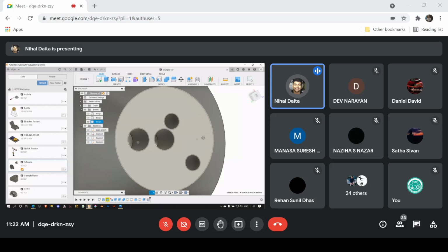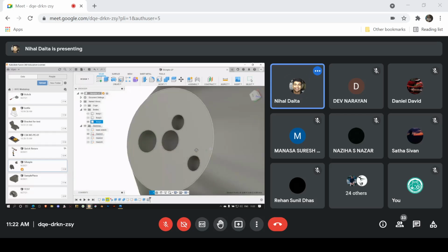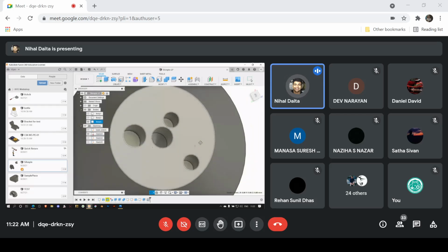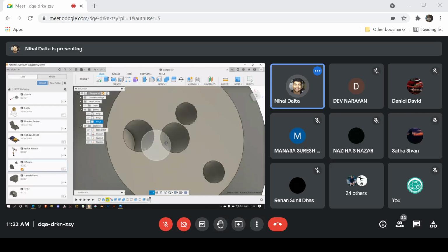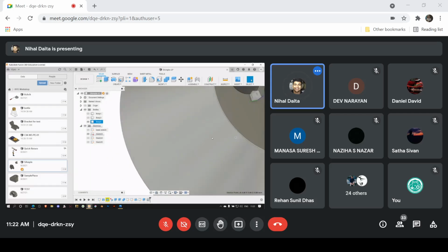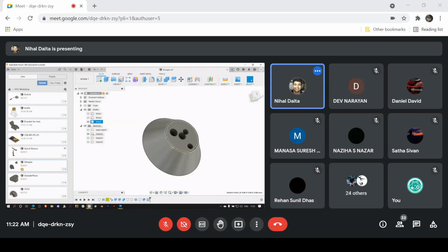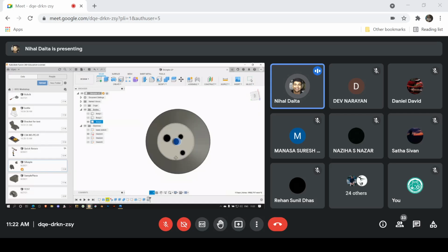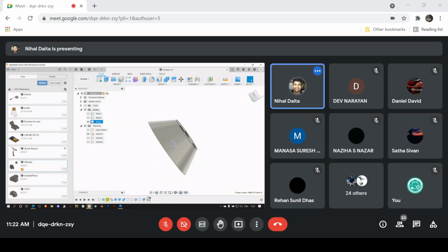But this has a point at the base. I really cannot show you that feature any clearer. If I were to select that feature and go to the side, you can see how it's conical at the end. So that's just the hole tool. I would assume you would be using extrude more often. That's fine. You can use the hole tool as well.